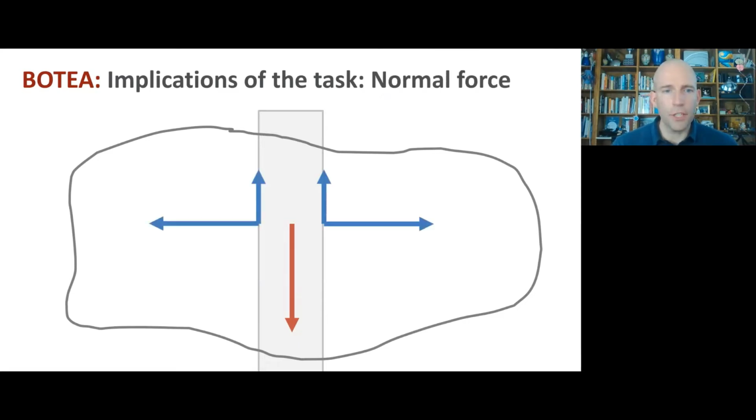And since it's coming from friction, that means we're going to need big normal force. These are forces of the door onto our potato robot here. So we're going to need some big outward forces to provide a normal force that allows for friction to develop. Unless we were using some gecko adhesive or another cool product that wasn't available to us for this project. Well, so this is one way to do that. We've got the force sort of centered on the door. We've got these vertical forces distributed evenly between the two faces of the door and some normal forces to get that.